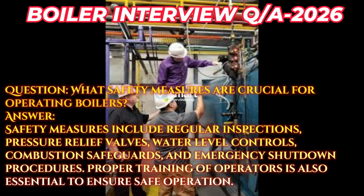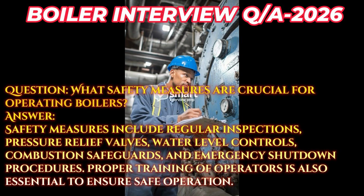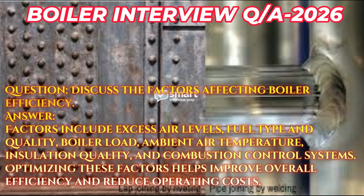Answer. Safety measures include regular inspections, pressure relief valves, water level controls, combustion safeguards, and emergency shutdown procedures. Proper training of operators is also essential to ensure safe operation. Question. Discuss the factors affecting boiler efficiency.